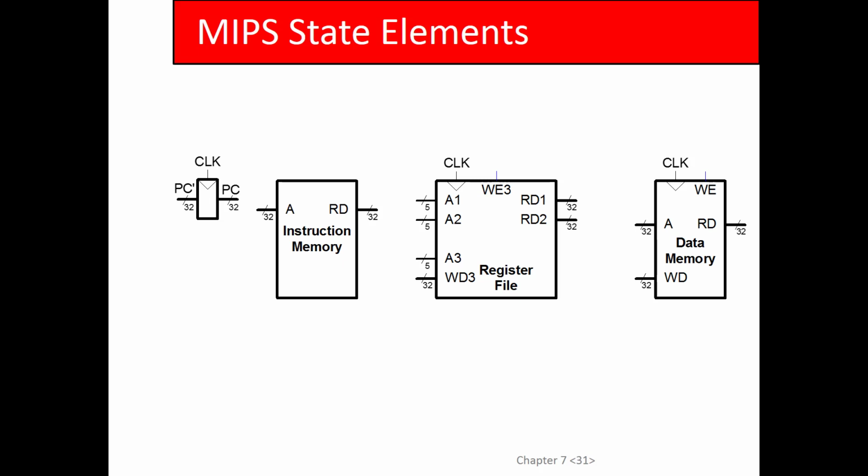There's also this notion of a von Neumann architecture, and then there's a Harvard architecture. There are 2 different architecture styles. Von Neumann architectures have a unified memory, and a Harvard architecture has a split instruction and data memory. So sometimes you'll hear people refer to this as a Harvard architecture. But the distinction is artificial because with memory hierarchies, even if you have split instruction and data memories at some point, eventually further down the memory hierarchy they're in a unified memory address space. Does that make sense? Okay.